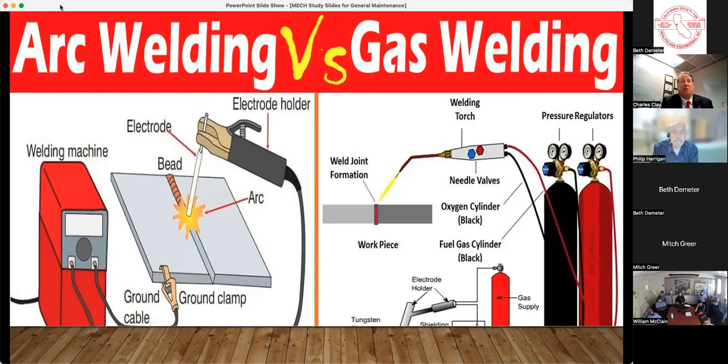A lot of people what we call strike an arc. You'll strike it, come across it, and strike it to get the first part of the burn. Then you'll make sure that you're hitting both pieces of metal equally, to make that fusion occur, and working your way down. When you get down, it should look like plates in a dish strainer. If you do a little dishwashing like I do, and laying plates side by side through there, you've got a great weld.